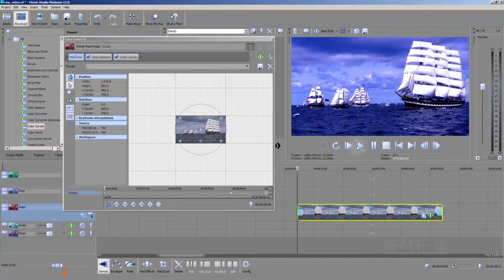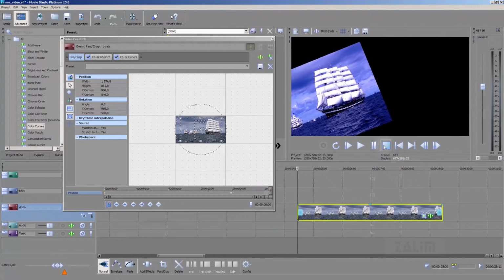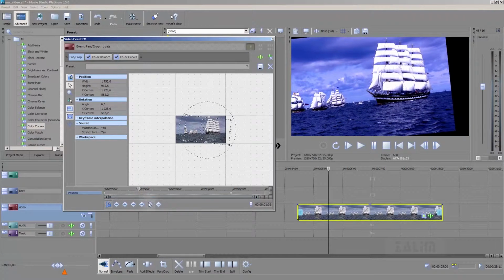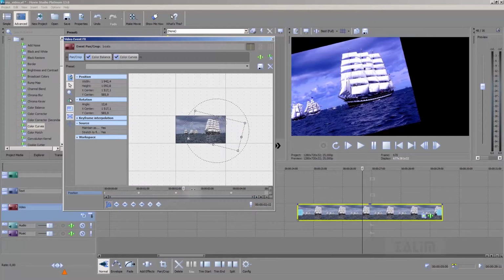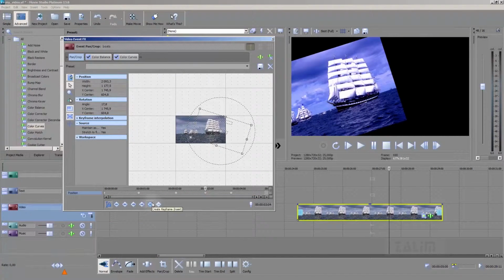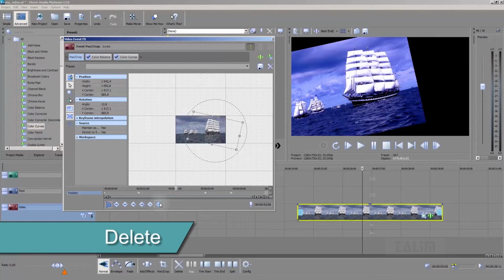Animation by keyframes. This change of the settings is in regard to the time frame from one key to the next. Under the timeline to the left, there is a set of buttons for working with the keyframes. Press the image key with a plus sign to add a keyframe in the location of the playhead. The shortcut key on the keyboard is Insert. Moreover, this keyframe saves the settings of the previous key. The key button with a minus sign deletes the selected key, as does the Delete button on the keyboard.